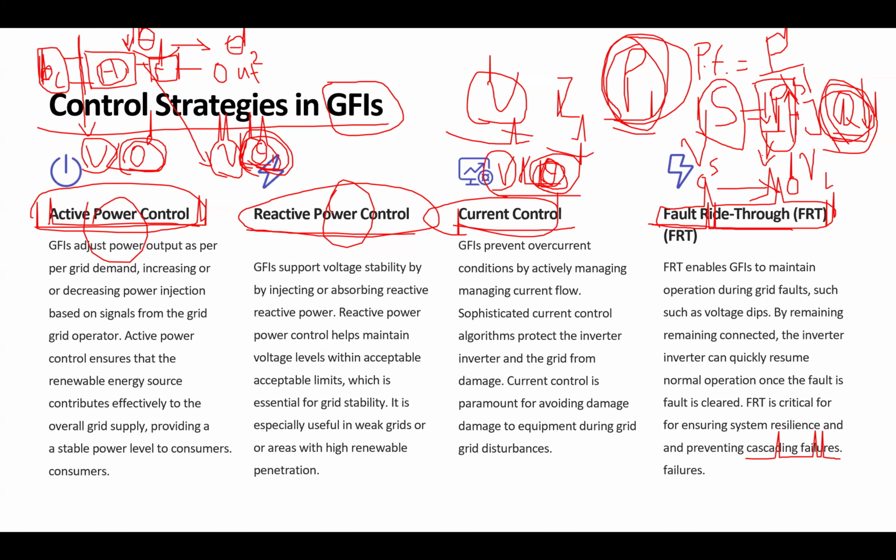When you have a rush of reactive power demand, meaning you have to consume a lot of reactive power, the reactive power consumption would lower the voltage of your grid. We said reactive power relates to the voltage, the amplitude of the voltage of the grid.